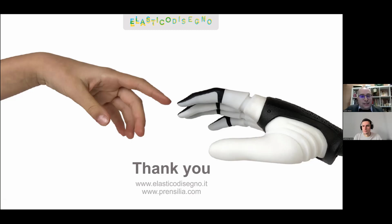So we dressed it on top of all the internals. All the actual parts were developed with Creo. So we took what we can call the glove, the hand itself, over to Creo, and then we started slicing it up and creating all the parts. So the extraction angles, draft angles, and all that were all done in Creo.